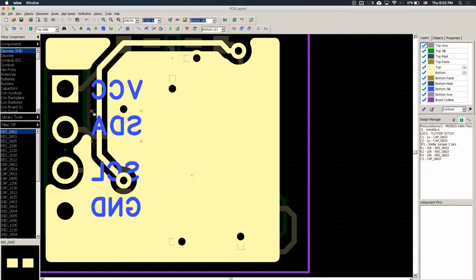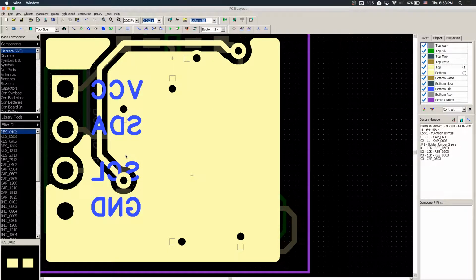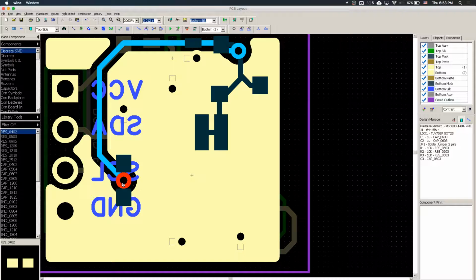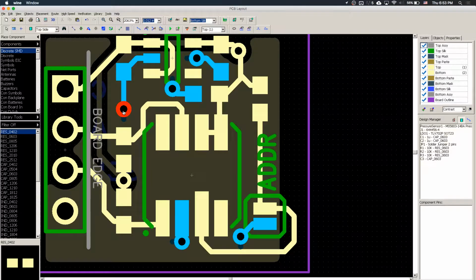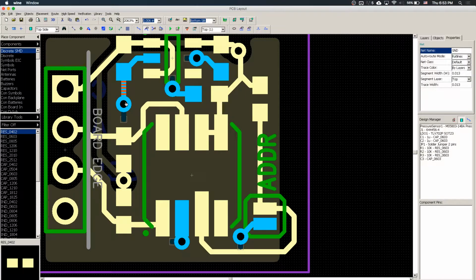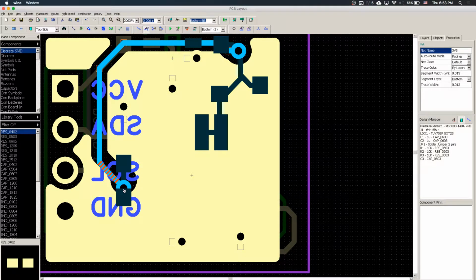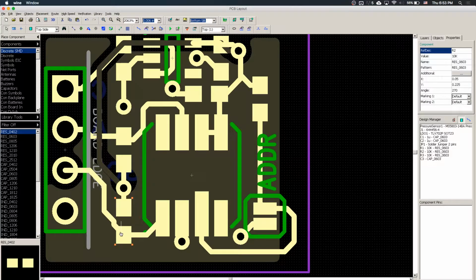One thing to be careful about is that a via will interfere with your text label, because a via is a drill hole and the text cannot be placed on top of it. So we're going to move our vias a little bit to fit our labels better. I'm going to move this a tiny bit up, maybe a finer bit. And this one a little bit down, and adjust those resistors accordingly.